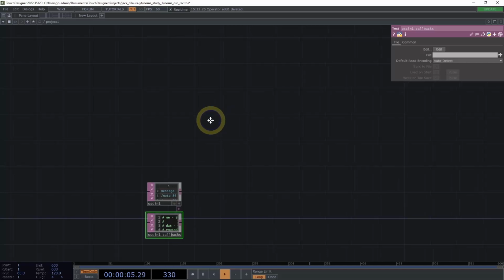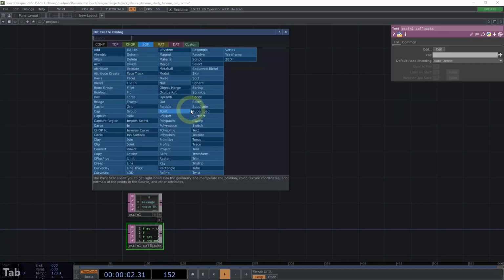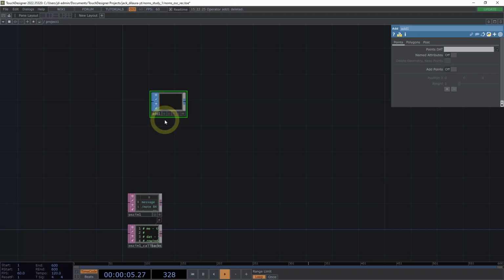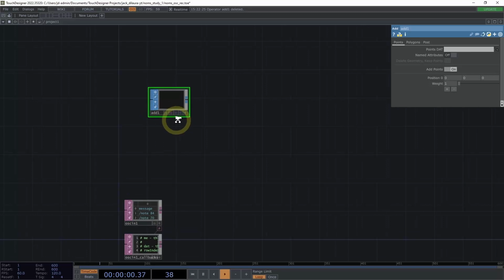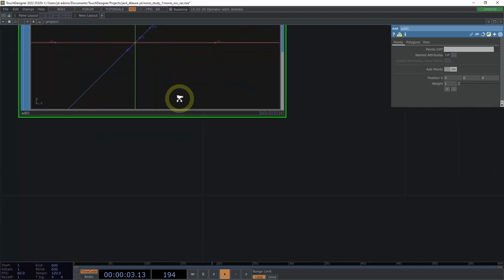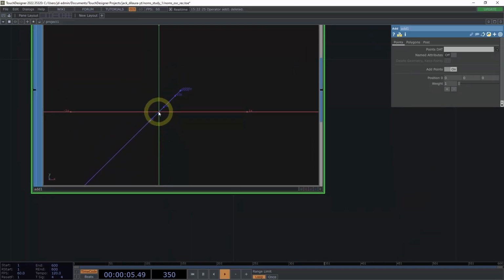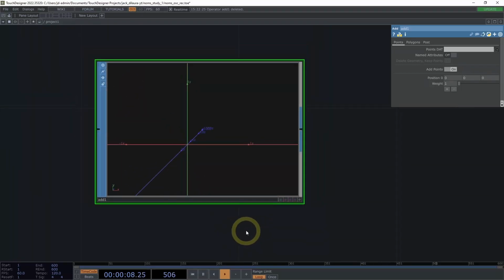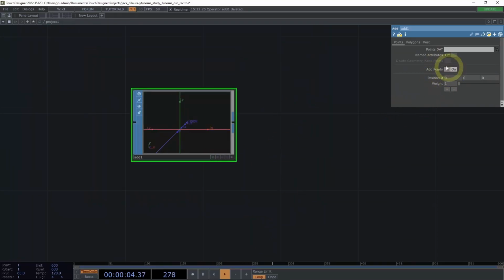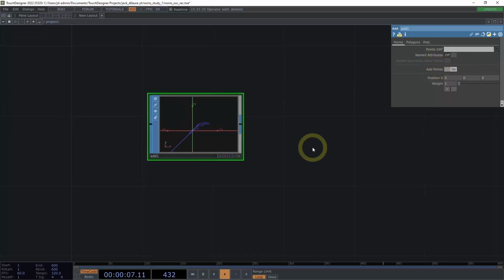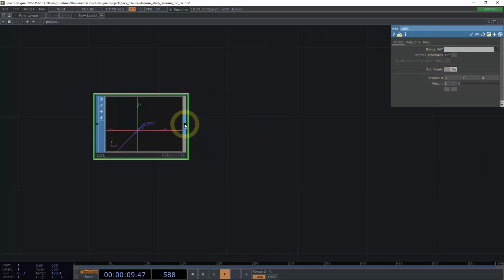So to start, we're going to be creating the geometry itself. Since we're going to be working with particles specifically, all we need to supply to start is a single point. To do that, we're going to use the Add SOP. The Add SOP has the ability, via this Add Points switch, to add a single point, which in this case is located, although we can't really see it, right at the center of all three axes. So within this operator, all we've done is turn on this Add Point switch, and now we're going to move on to our next operator.